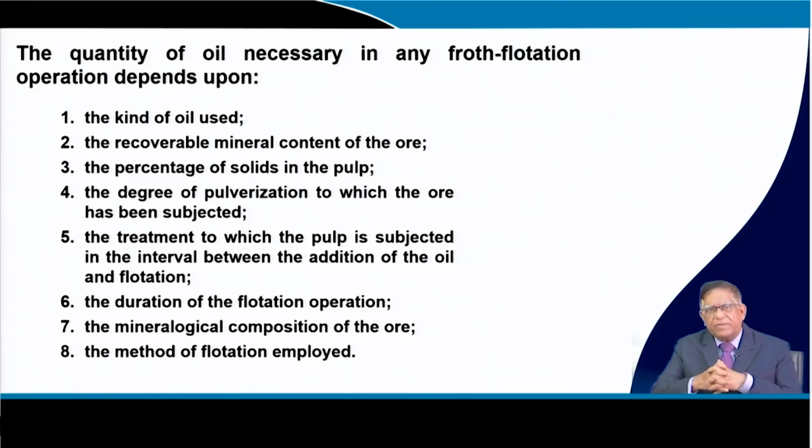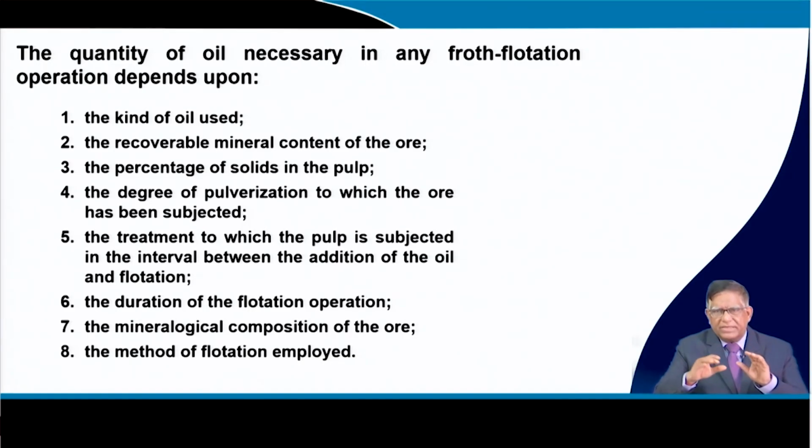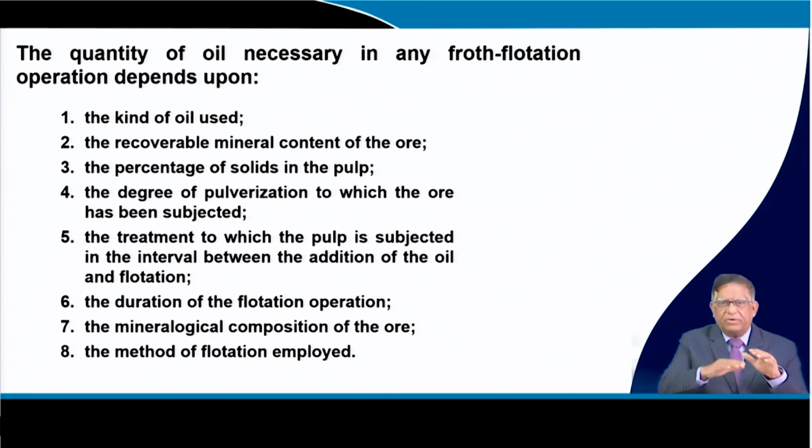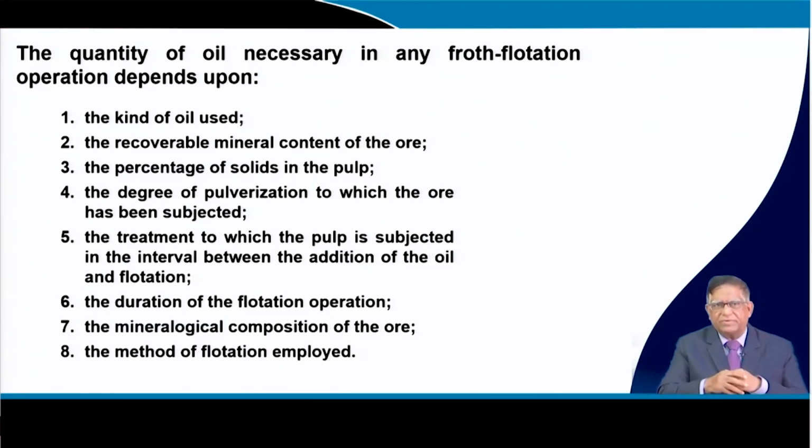The duration of the flotation operation, that means how long the material is there, and once you have introduced the slurry over there and then the oil and all things in that media, how long these bubbles will be staying, going and getting raised toward the top. This is the retention time of the floats; at that time there will be interactions with new bubbles coming, and that duration is also very important.